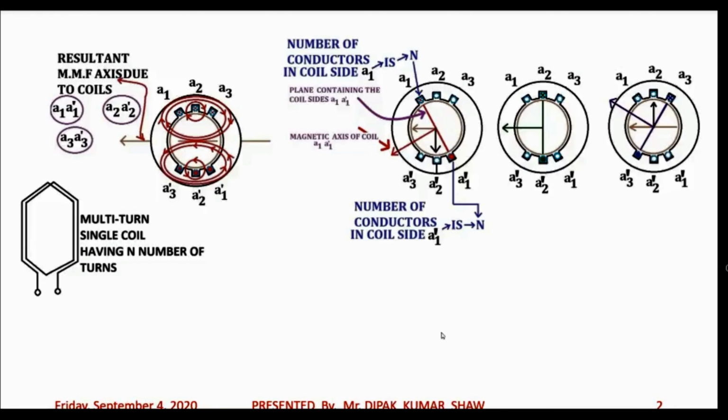But yes, before I start, I want to again mention a very important thing. When I am saying that the MMF in the air gap of a single phase induction motor is stationary and pulsating, here I have made one assumption which I have not stated explicitly. So what is the assumption which I have made? I have made the assumption that the single phase induction motor is having only one winding, that is the main